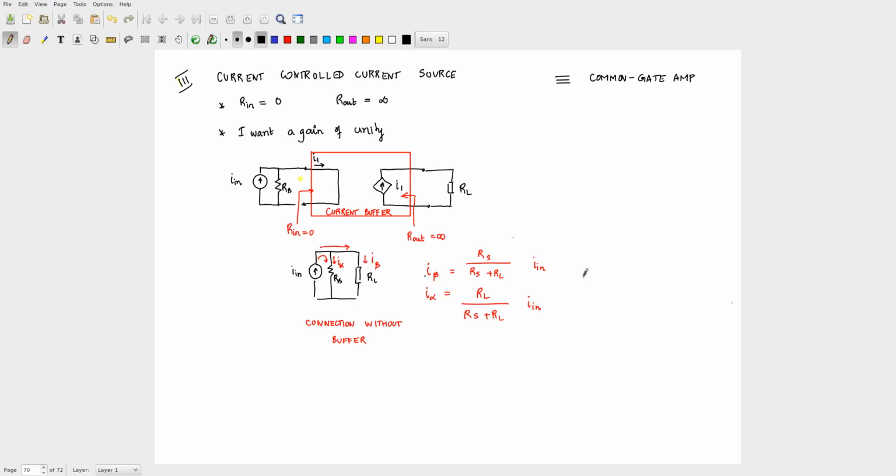You bias the diode at a certain voltage, and based on the amount of light that is falling, the amount of current will change. So the current is your signal. You want to buffer that current. So what I am drawing here is an incremental current source. Just as you had an incremental voltage source, you can have an incremental current source also. There is no problem. These are all incremental quantities that I am drawing. It so happens that the incremental quantity is a current source.